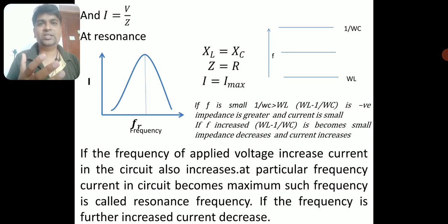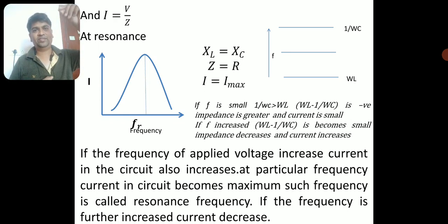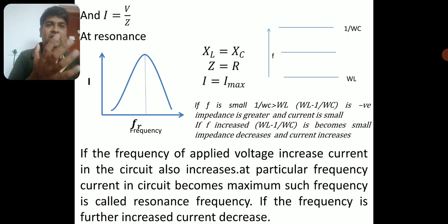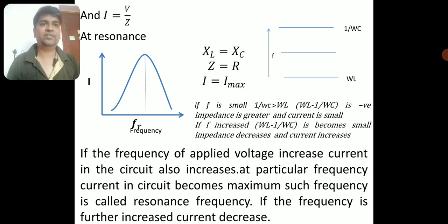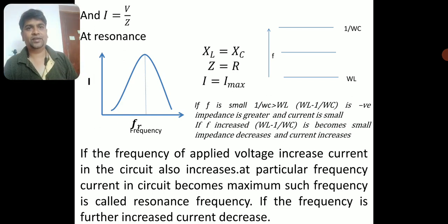If impedance is greater, it means the current will decrease. So after the resonant frequency, the current will start to decrease again. That was satisfactorily explained with this kind of analysis. That is why in a series LCR circuit, current increases, and then after the resonant frequency, current decreases.